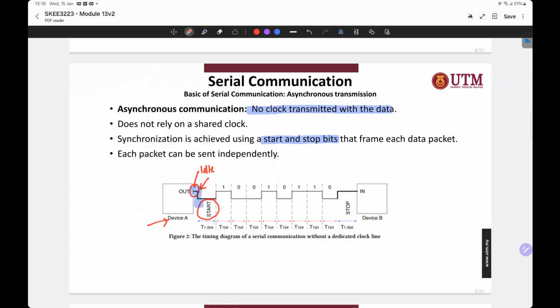And after a short time, which in this example is 1.5 bit periods, the sampling of the bits will begin. Once the CPU knows that a negative edge was triggered here, a falling edge, then after 1.5 bit periods, the next signal will be the data sent out from the transmitter. So this is how the receiver knows which data is sent.